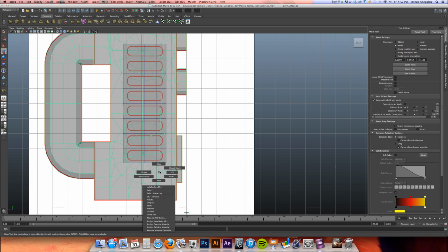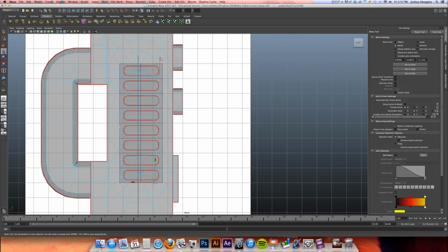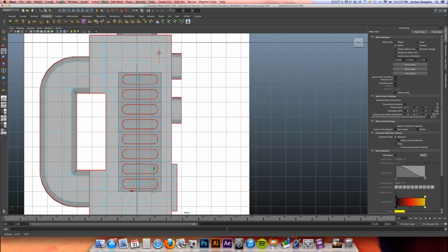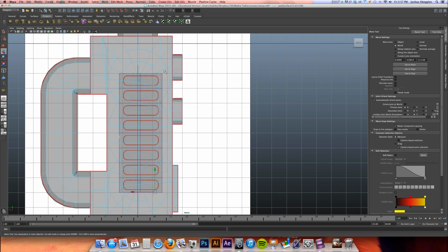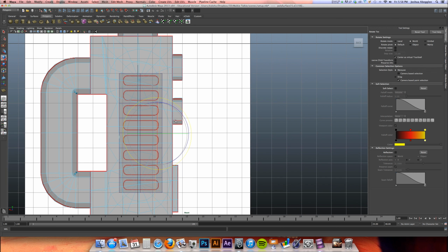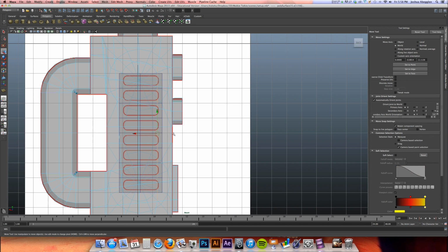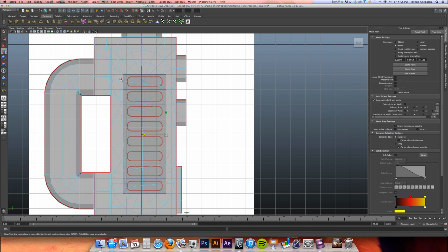All right, so what I am going to do is I'm going to grab this edge, hold down Shift, and come up here up to this edge right there. Now I'll use my scale tool, just scale those laterally, and then use my translate tool and bring them over here and line them up with this plane that we had previously set up for reference.